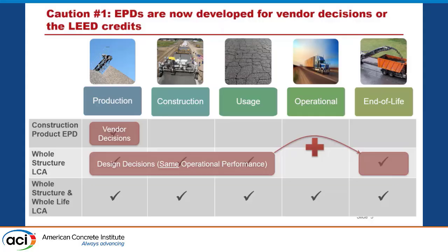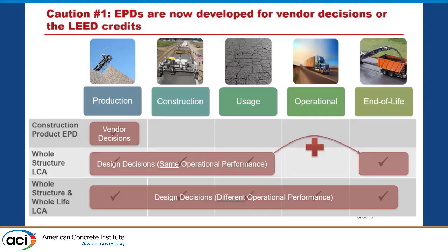But we have one step further, which is whole structure and whole life cycle LCA, where it's again at the design step, but we expect a different operational performance. For example, the energy consumptions during the use phase are different. Again, EPDs cannot answer this question in a comprehensive way because they only include the information about the production of these